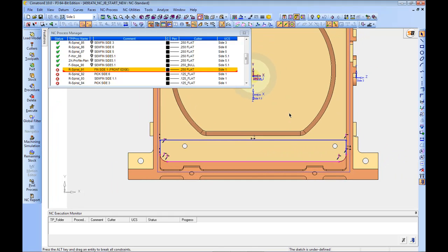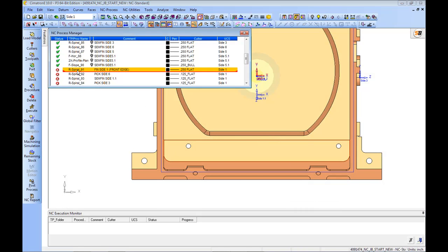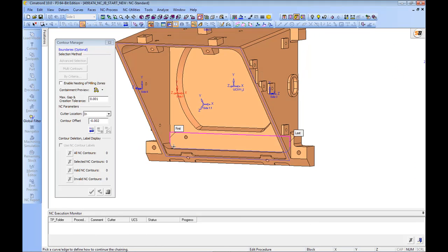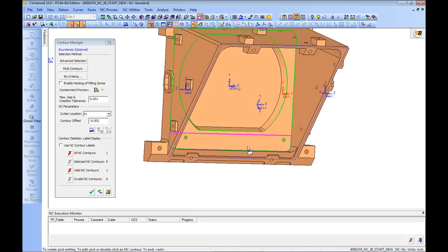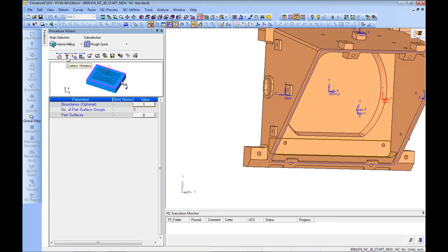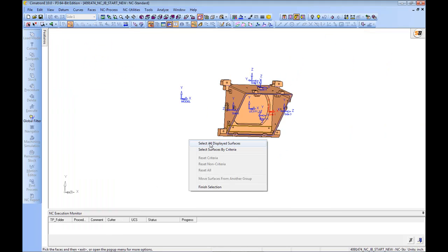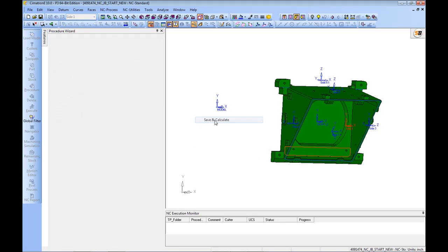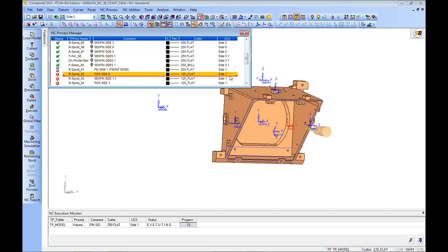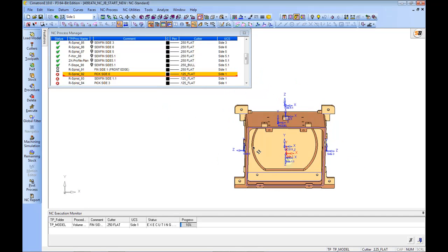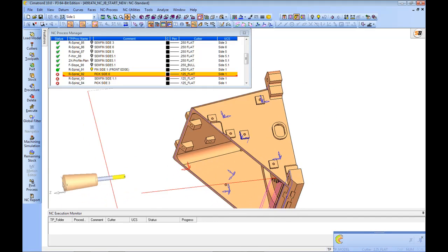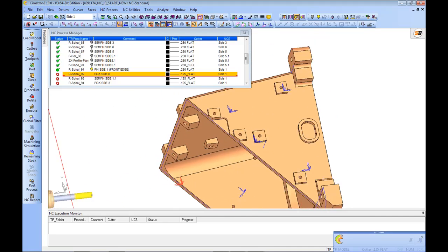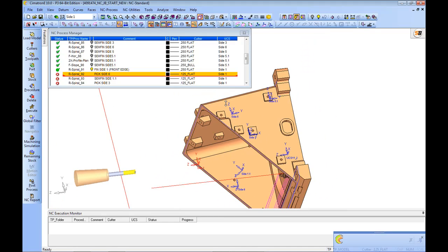That looks pretty good. And then we're going to go here, boundary, part surfaces, we'll just say all, and execute. Next, now we're going to do picking over here on this side. Or wait a minute, side 6 is the left side.